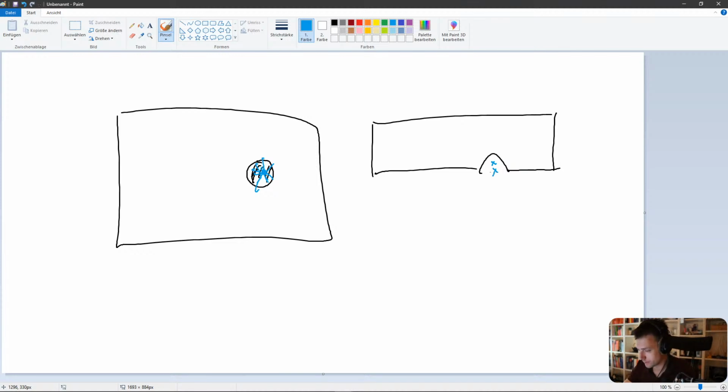It's a tricky question, and I struggled with that myself, to be honest. I thought it should be at the center, because that's what's happening, right? But the reality is that you're introducing a bending moment. And this is not something which the symmetry constraint will cover. So just think about looking from this side.